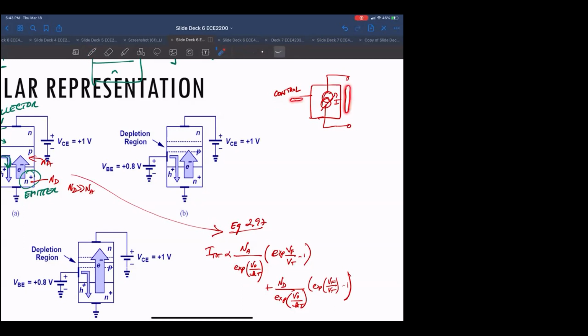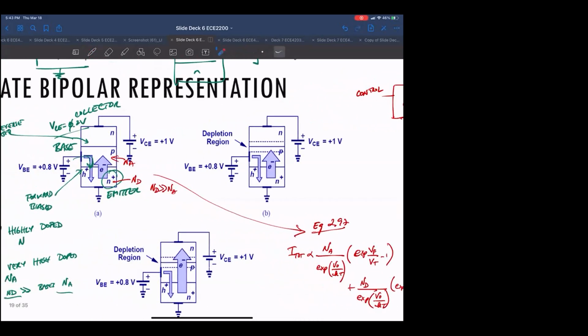That's a very efficient transfer function. This current is the input of the transistor in this mode of operation, coming from whatever is driving the circuit, which has to source that current. You want that to be low compared to the current you're controlling, which is this emitter current. You do that by making this much higher doped than the P. So that's the purpose of that.